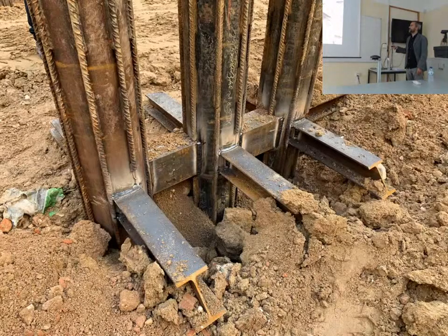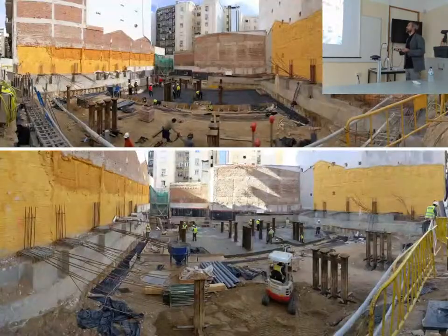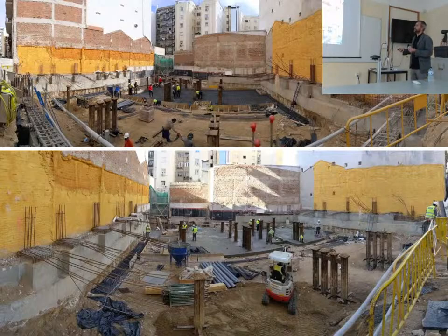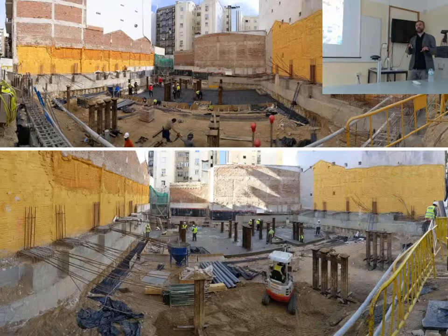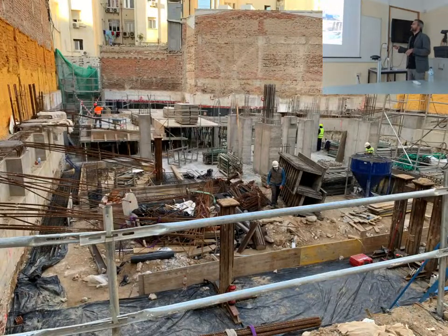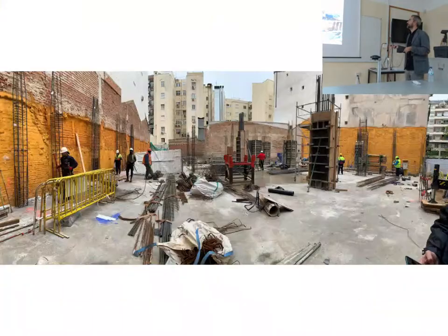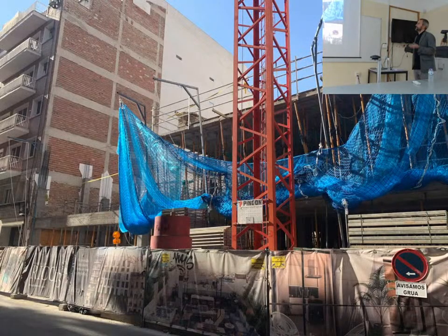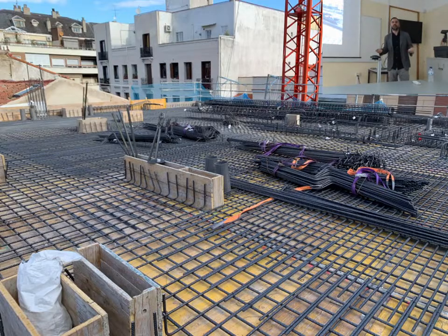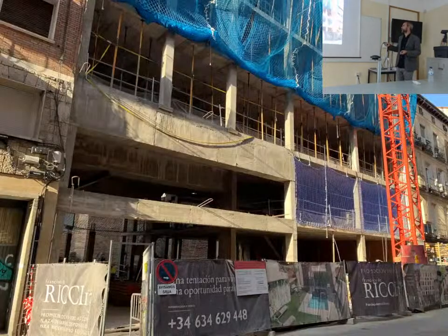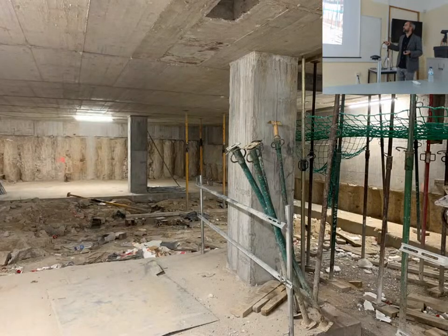So you have all these connections, and also all these connections for transferring the loads from the concrete to the micropile. Okay? So we directly pour the concrete using the soil as a formwork, on the -1. You see the columns, but below we don't have any foundation, we only have these micropiles connected. Okay, so the building is going up and going down at the same time. Because you see we are constructing the different levels. They are standard concrete slabs, with some beams at some levels, but nothing very specific.